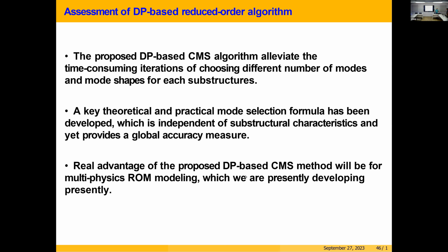The fundamental solution in the partition formulation means that when each partition is floating, its rigid body mode is the fundamental solution. So you get the fundamental solution, which is a rigid solid. When you chop it, you get forces transmitted without any deformation.